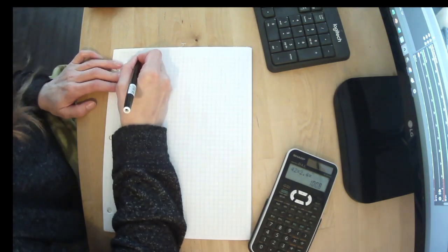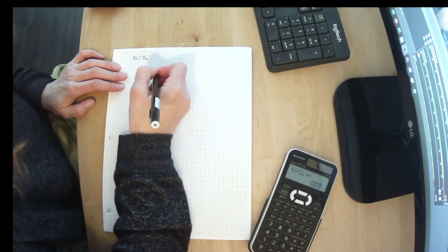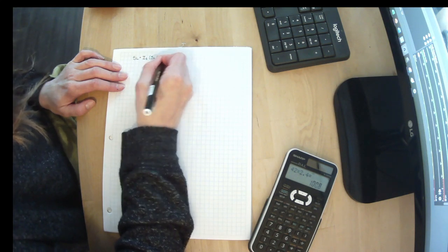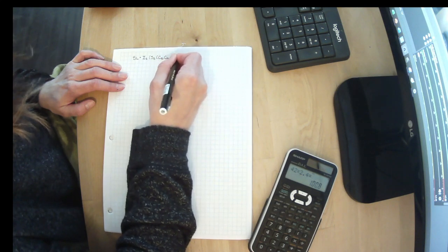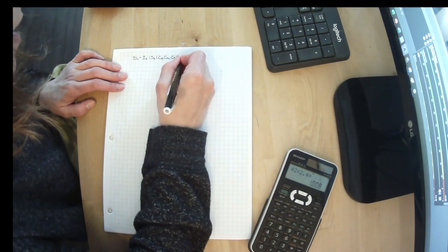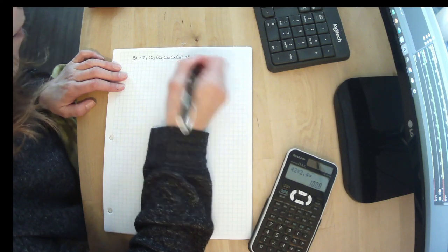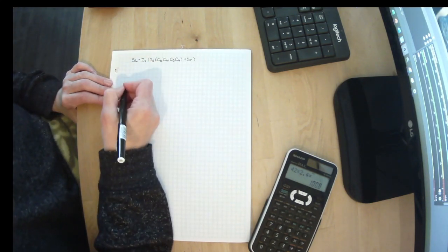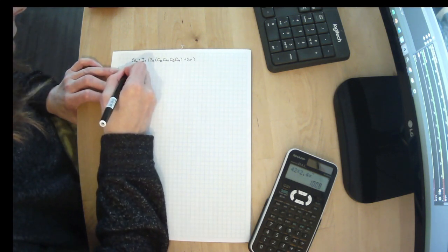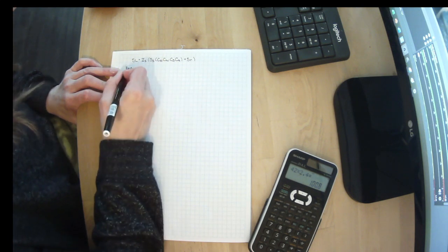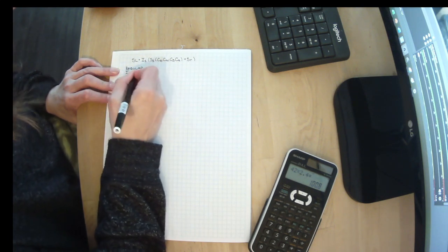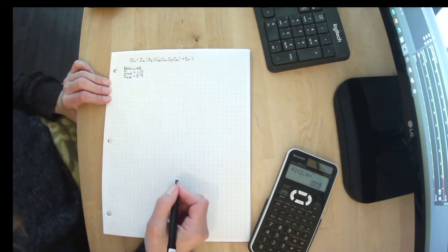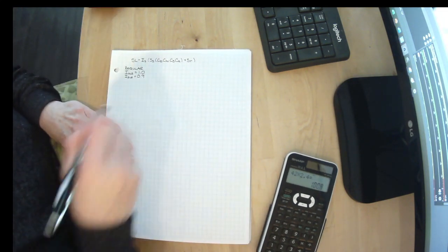So snow load, we know that the equation is our importance factor for snow times our SS, which is multiplied by CB, CW, CS, CA, plus SR. Well, for our importance factor, if it is regular, IULS is 1, and ISLS is 0.9. I gave you that chart, and it's in the slideshow that shows you those.